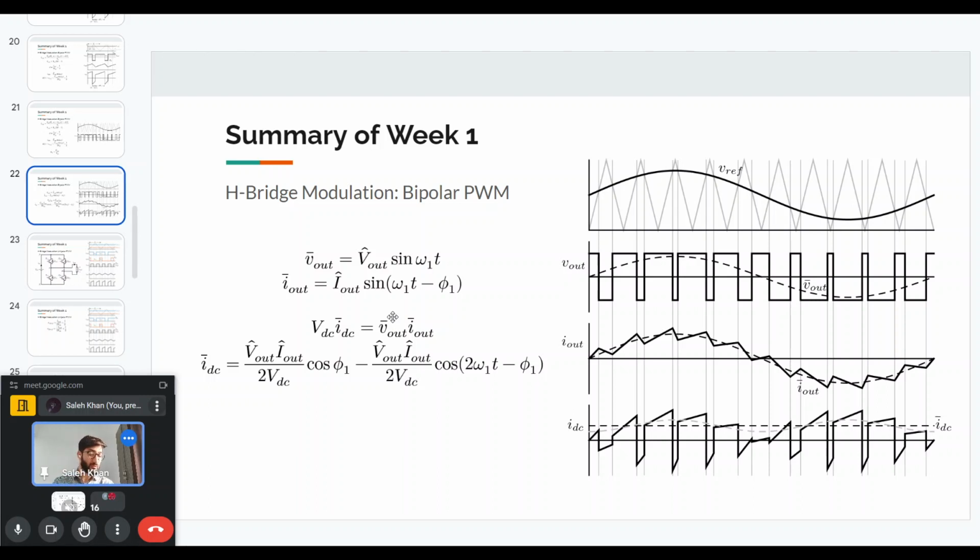You may have to use silicon carbide or gallium nitride devices, or you may have to do some liquid cooling or some soft switching techniques. So a lot of factors come into the switching frequency, but it is basically a trade-off between efficiency or losses versus the filter size. Depending on what you can allow, you have to choose the switching frequency in that way.